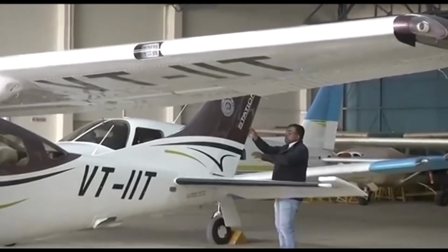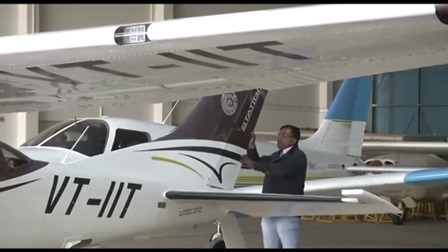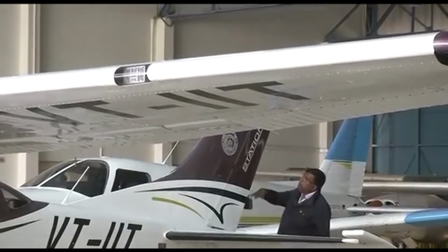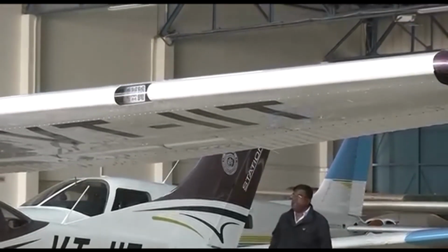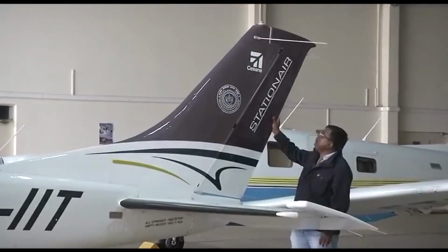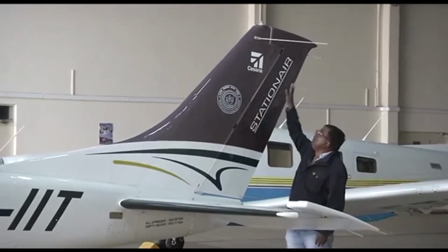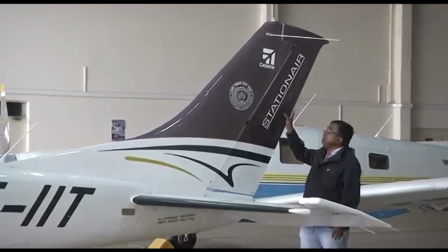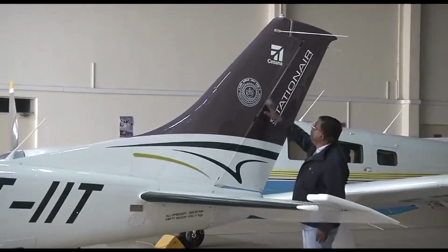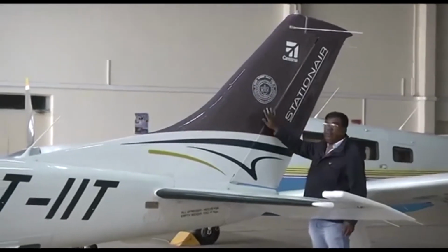See, it goes towards left, goes towards right. And you could see it's a very appreciable size of vertical tail. Please carefully see the rudder is this portion. When I take the total area, which is the vertical stabilizer, the rudder is almost 40% of it, 35 to 40%.